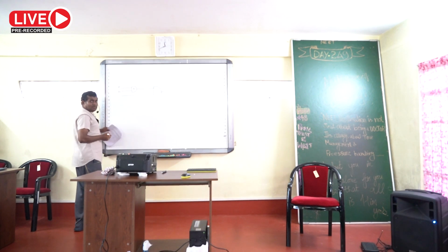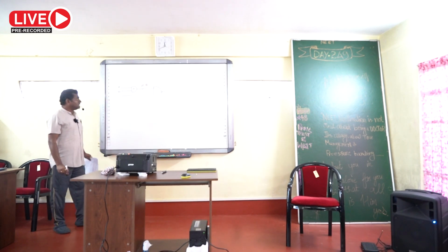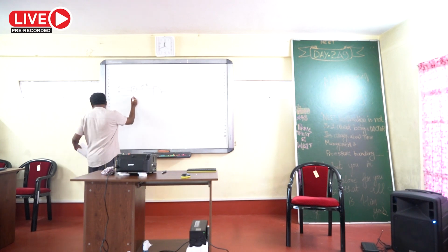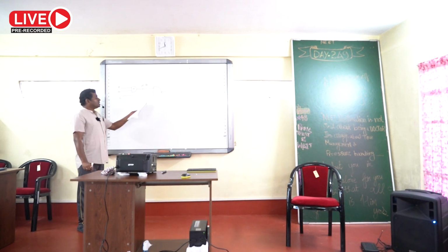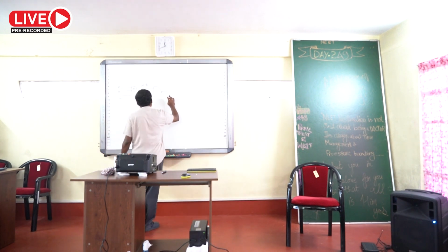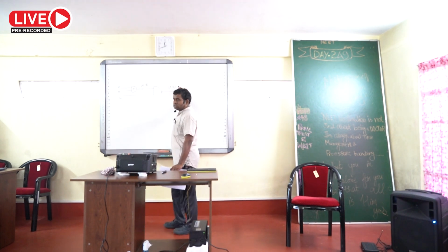Here A and B are given. So on this channel it will be A into B, AND gate. Then this one is given another input C. So now first it will produce A into B into C, and then not.